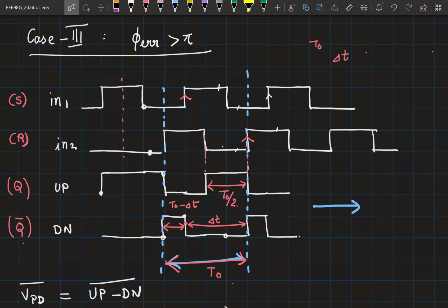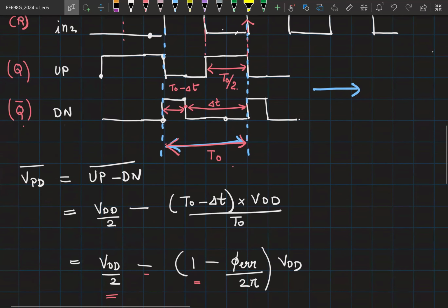Which means my phase detector should only be a function of one of the edges. And if you are measuring delta between the rising edges, it should only operate on the rising edge, right? So in this line of thought, what is the first element that comes to your mind when I start saying this? It should be flip-flop, right? So now you can also build phase detectors using flip-flops.